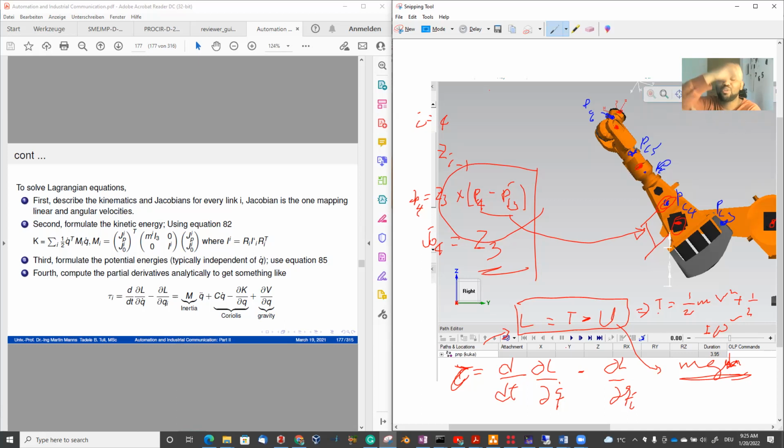And we say joint space because it is a robot joint, which is in angle. Joint space is in angle, operational space is in XYZ, in the Cartesian coordinate system. That's why I said we will have operational space and joint space. We have a homogeneous transformation matrix. Its purpose is to derive the kinematic chain from the base to the end effector by calculating based on a joint space theta.